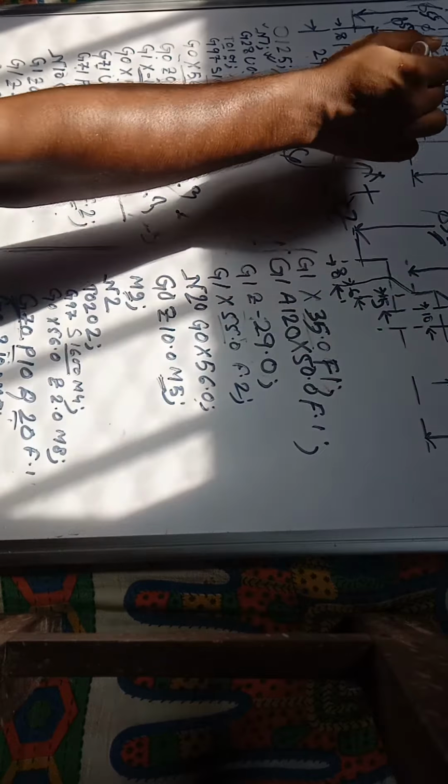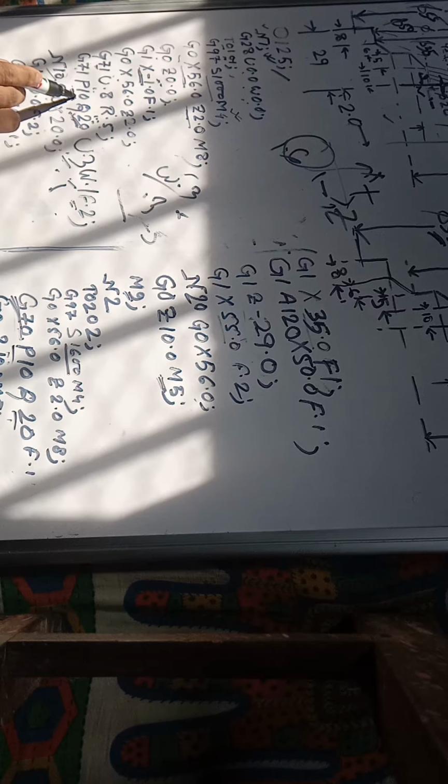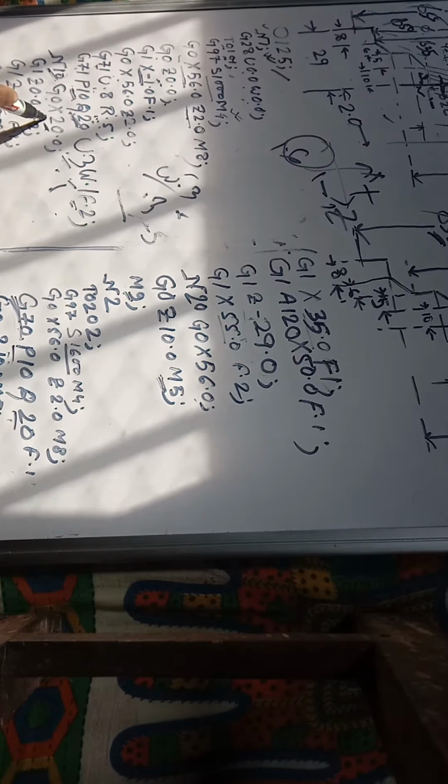After this you have to make this profile. So how will you do it? We will start from the minimum diameter. That is 20 mm. So we will start the sequence by means of N10, because we have mentioned that the starting sequence is P10, so we have to start with N10, and with the minimum value, 20 mm diameter. So we have to give G0 X20.